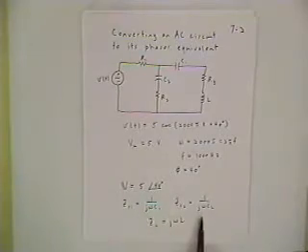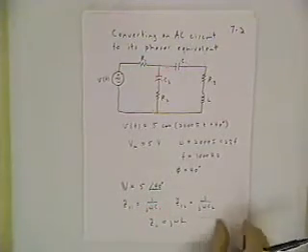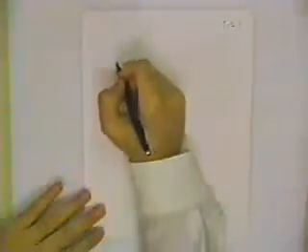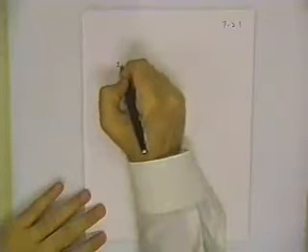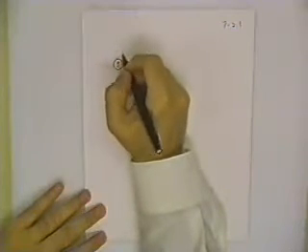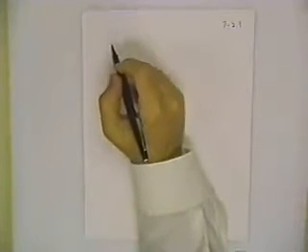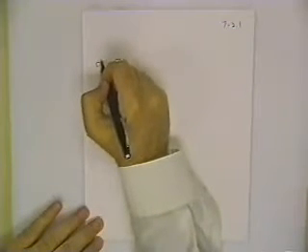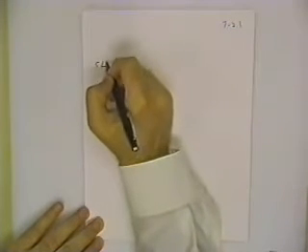Now with all of these substitutions, we're going to come up with a different circuit, a phasor equivalent circuit, or an impedance model for this circuit. And I want to show you what that would look like. You can use just the generic symbol for voltage source, because if you label it with a phasor, it's pretty clear that you're talking about a phasor equivalent.